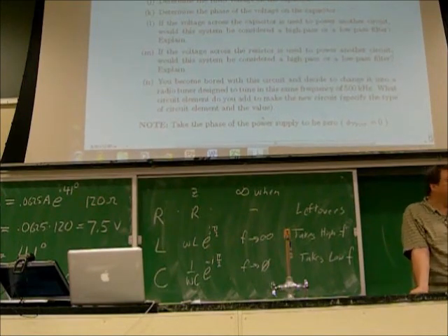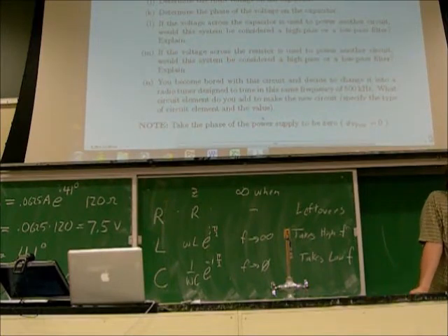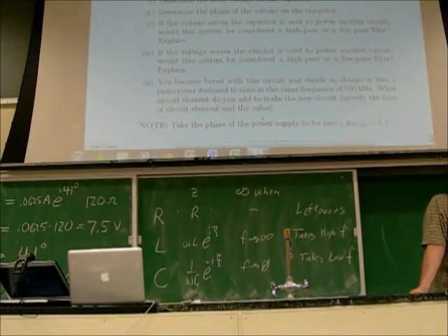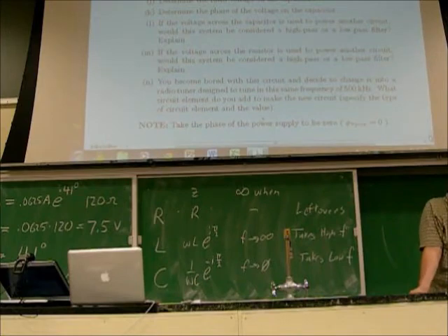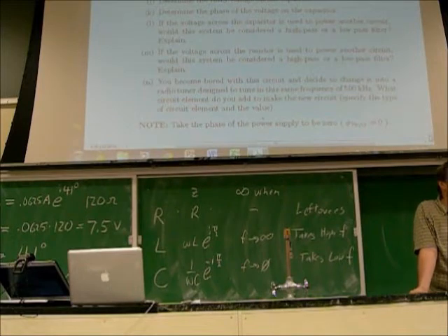The 12 volts was completely gone. But the little blips that were the signals were there completely and entirely. Why? The 12 volt is a DC signal. It's zero frequency. It all goes to the capacitor. And by putting his circuit in series with the capacitor, his circuit was the resistor and got only the high frequencies. And the 12 volt DC was totally gone for his circuit. Everything was cool.